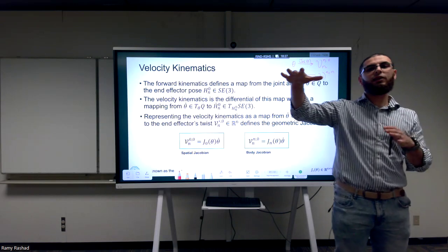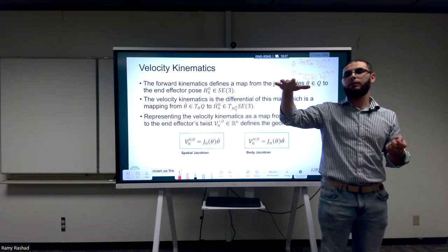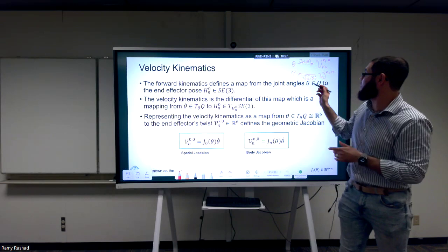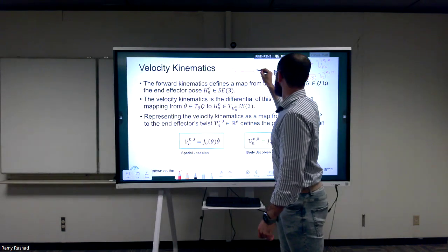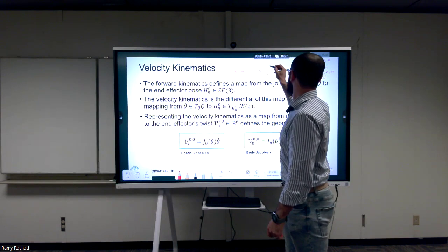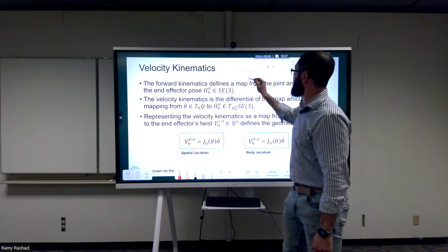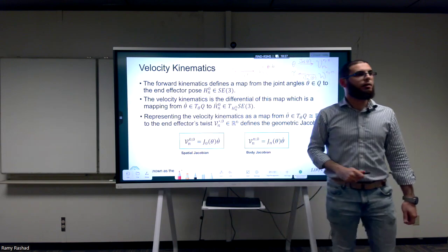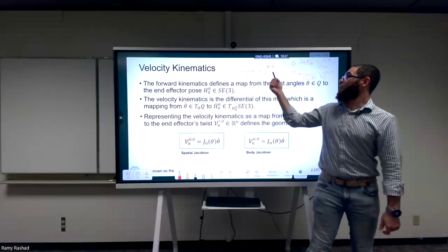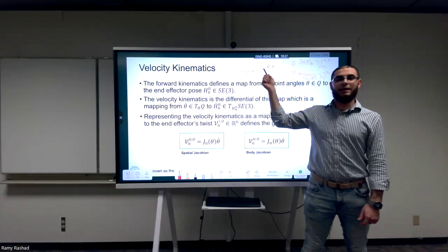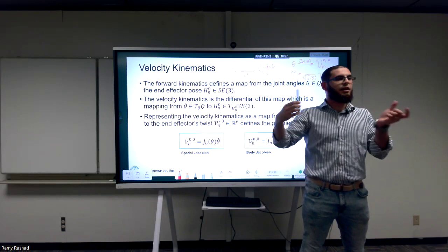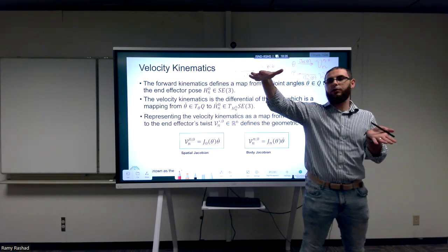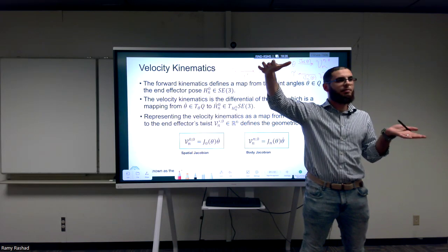What's the basic thing of any drone? Hovering. In the hovering, again, we have a map that goes from the lambdas to the wrench of the control, applied on the body, expressed in the body frame. And this map, we called it M. So if I want the total wrench applied on the drone to cancel the gravity, what does canceling the gravity mean? It means hover. If something cancels the gravity, it means it's hovering.